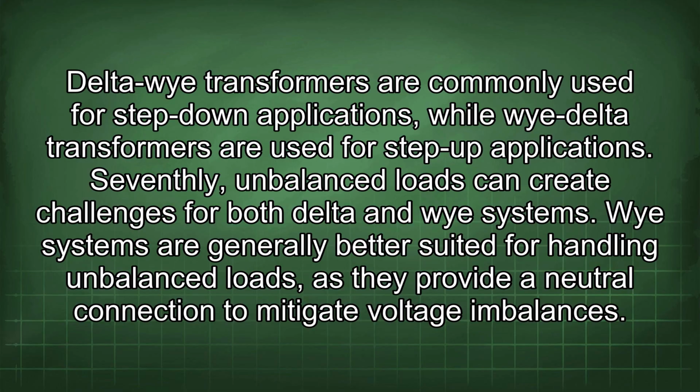Seventhly, unbalanced loads can create challenges for both delta and Y systems. Y systems are generally better suited for handling unbalanced loads, as they provide a neutral connection to mitigate voltage imbalances.